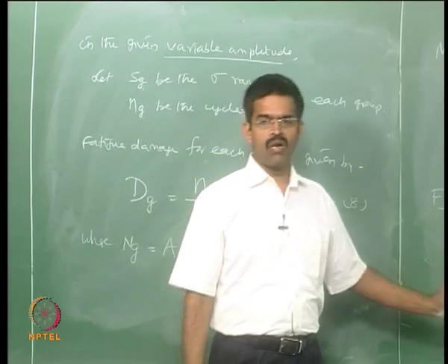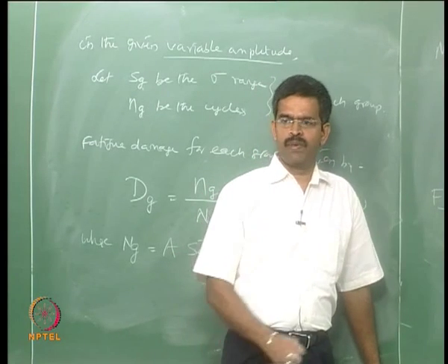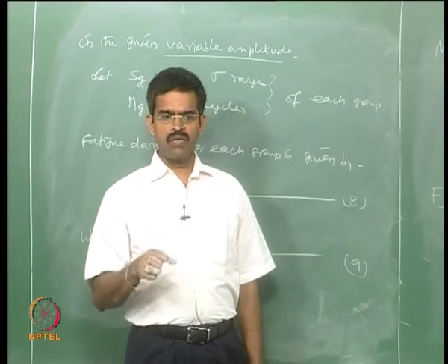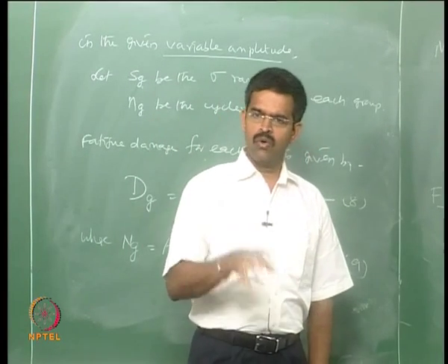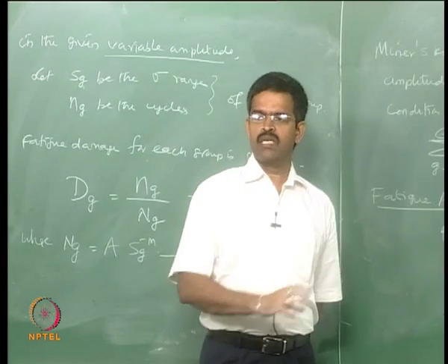But here the stresses can be compressive as well, and there is a mixture. So, the conventionally available SN curves, though they remain conservative, cannot be directly applicable to marine structures.